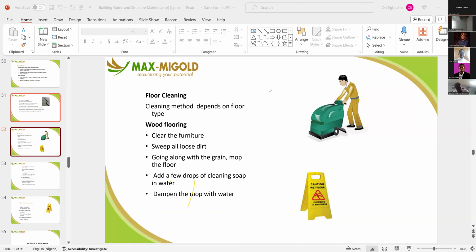Once the crack happens along the expansion joint, there is no need for panic. Even if it's just building settlement that's causing the crack, there's no room for panic, because once it settles just once, the building will take its level and you can continue enjoying your life. But if it's as a result of failing of the foundation, the crack will continue to increase, and once that happens, that building will be marked for demolition.